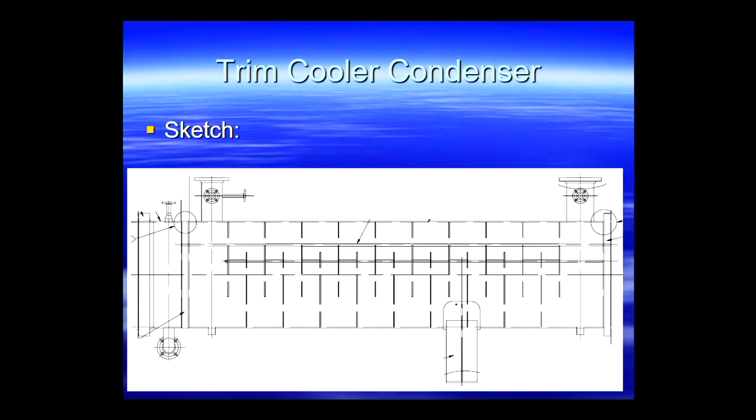And you can see that it is a standard shell and tube heat exchanger with ordinary single segmented baffles. That is, they've just got a chop, and as you can see, the water flows in one, up and over each of those baffles until it eventually disappears out the other end. Lots of dead pockets in there, very poor design. Water flow wasn't enough, consequently the temperature on the condensing nitric acid side went up, and there was buckets of corrosion.